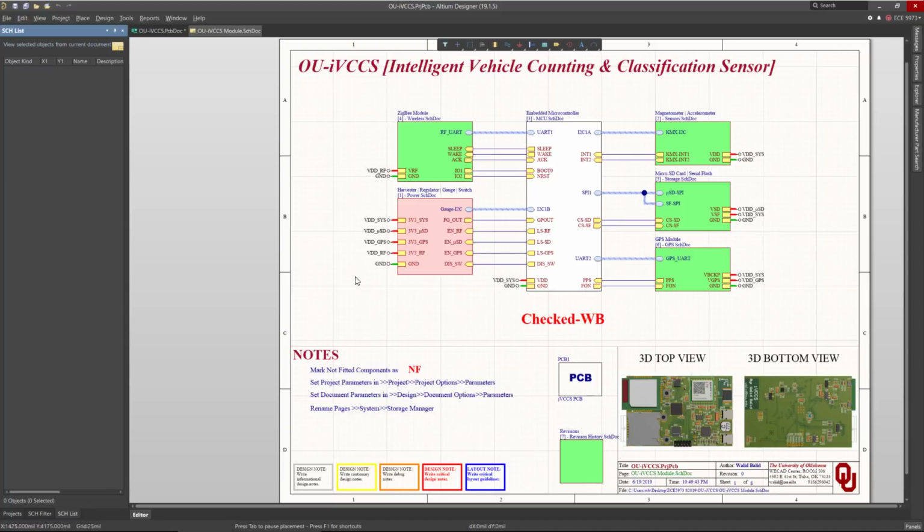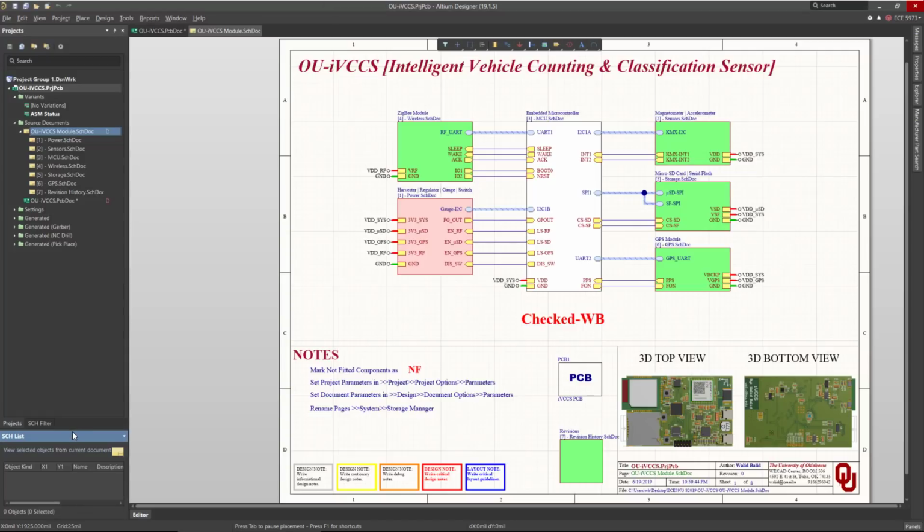The second one is called fractal panel grouping, which allows multiple panels to be grouped and visible at the same time. Now to group the panels in this fashion, just drag the source panel towards the small arrow icon. So let's take this one, for instance. If you drag it to the small icon on the top or on the bottom here, and here we can resize. Now you can see the properties panel and the schematic list panel at the same time.